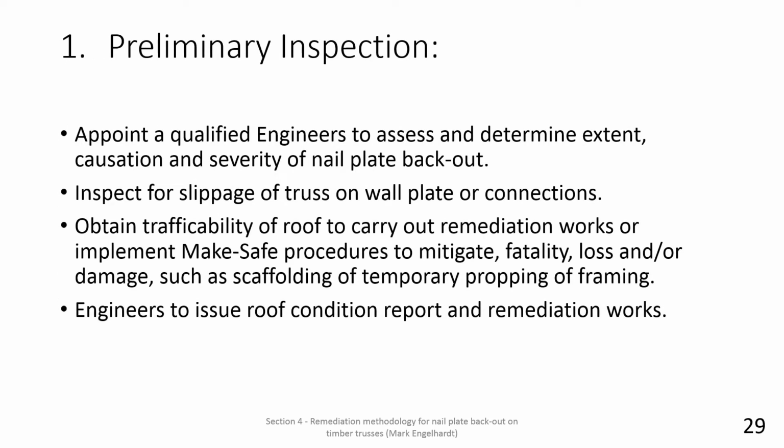In consideration of the technical skill and severity of risk associated with truss failure, it is recommended that a suitably qualified engineer should be appointed to assess and determine the extent, causation, and severity of nail plate backout, and if necessary, provide a remediation scope of work and/or make safe to mitigate harm or further damage.